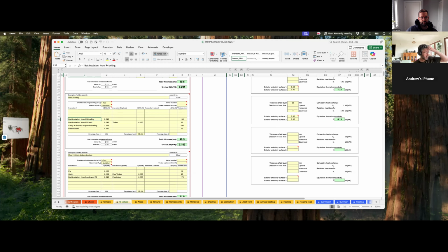The reason I've got the two layers of insulation is because if you have one layer of insulation between your ceiling joists, then there's nothing above your ceiling joists. An alternative there is, if we can fit it, there's some new bats on the market that are R7 or R8, and they're deliberately wider, so they will squeeze between the ceiling joists, and then above that, they will come together and cover that gap.